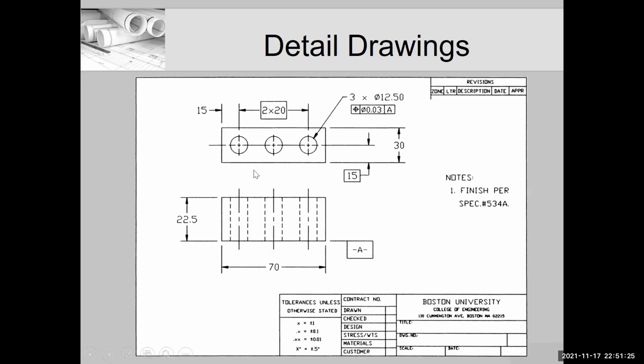Let's talk about that. Top page, assembly drawing, possibly some sub-assemblies under it, which are very similar to the overall assembly, except that they're just taking a part of the overall object and showing it in assembly. I'll show you that as well. Detail drawing. This should look very familiar to you. This is a top view. This is a front view with dimensions. This is a 3-hole block.